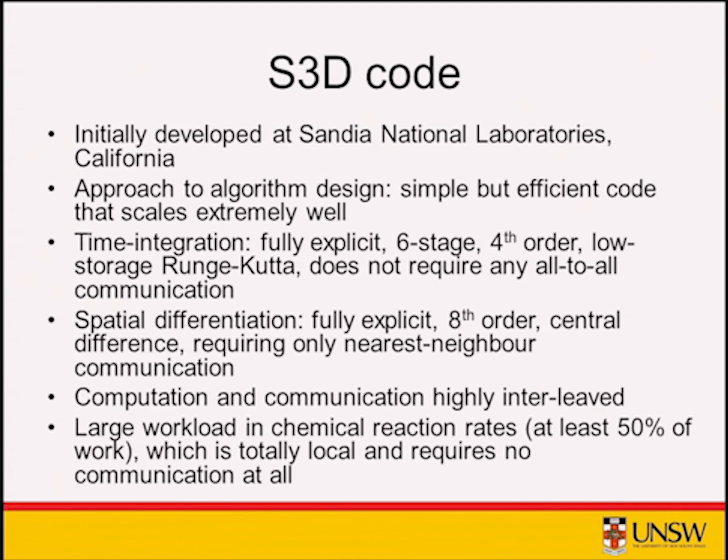The time integration is fully explicit, which notably doesn't require any all-to-all communication. Spatial differentiation, again, is also fully explicit with no all-to-all, only nearest neighbour communication needed. We also take a lot of effort to minimise the amount of time waiting in computation. We do that with MPI rank placement, according to the memory architecture, as well as interleaving the computation and communication. And we have the advantage, like all combustion people, of this large point-wise workload that doesn't require any communication at all in the chemical reaction rates.